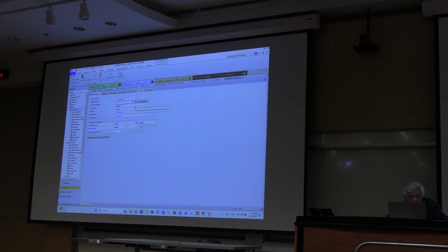You don't really need that many. Probably between 20 to 25 will be enough. Mass reflux ratio 5 could be high. You can lower that as long as you get a desired mass fraction of ACN.